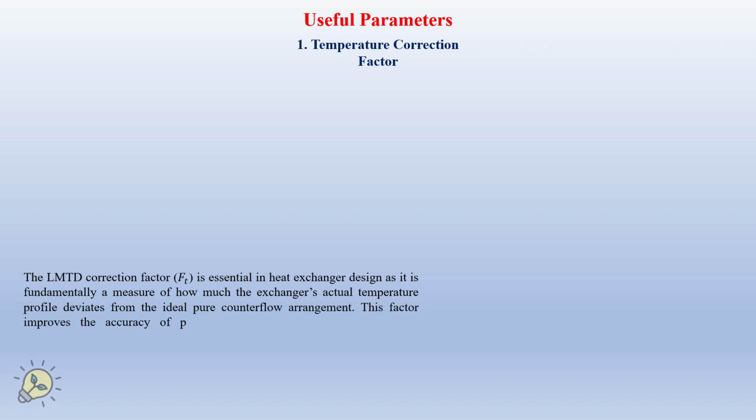It accounts for that deviation because the main idea of the derivation of LMTD was based on a pure counterflow in the heat exchanger, and this correction factor is usually used to produce a more accurate design of the heat exchanger with optimal efficiency.